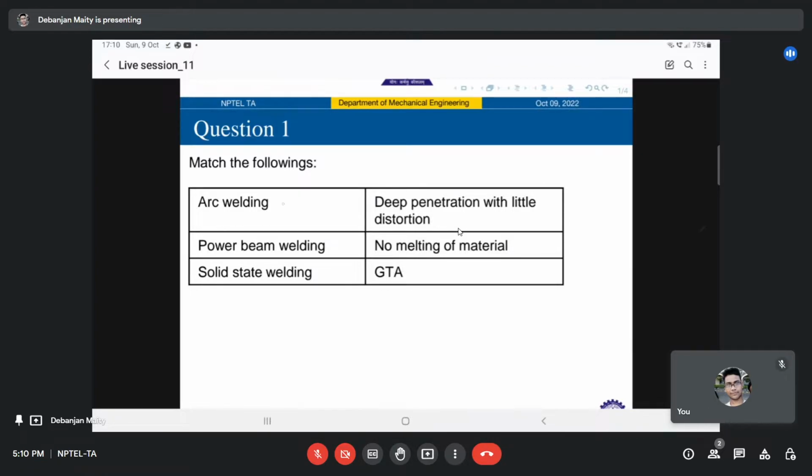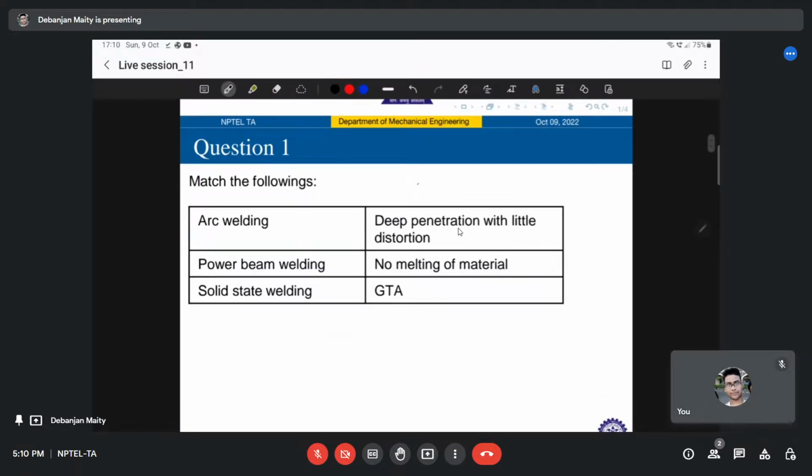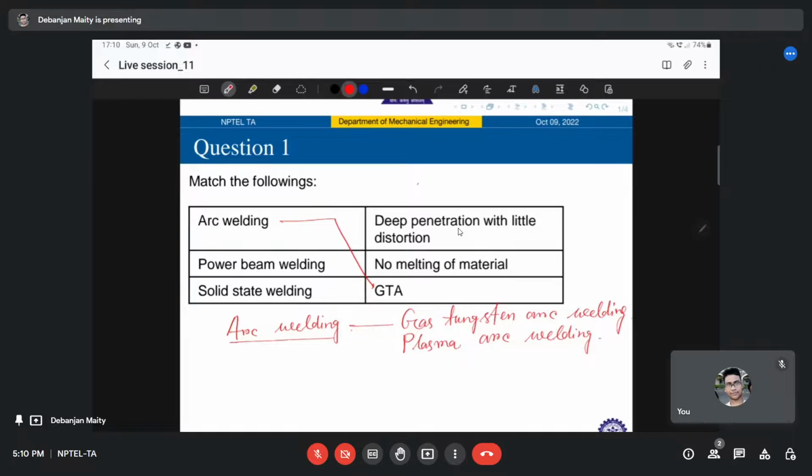In gas tungsten arc welding and plasma welding, the peak pulse controls the penetration, and the background pulses allow solidification without extinguishing the arc.